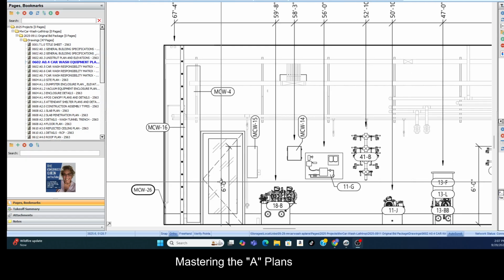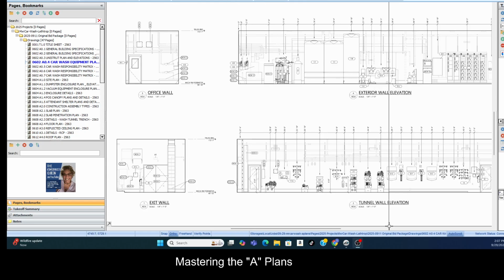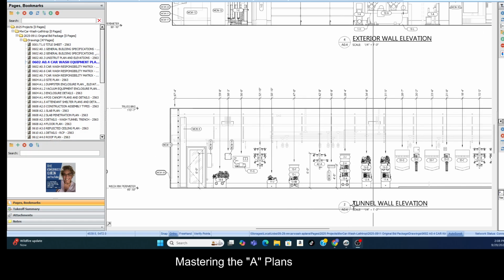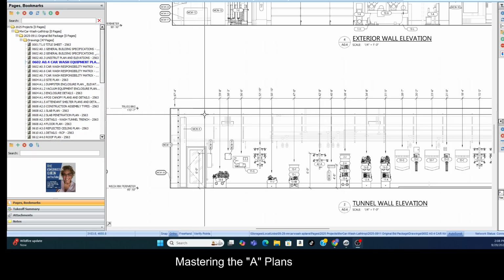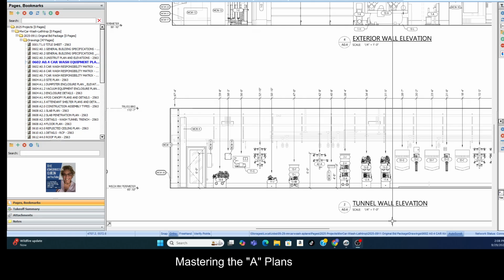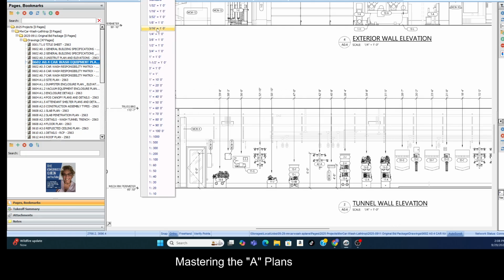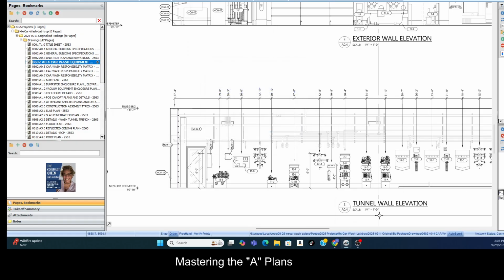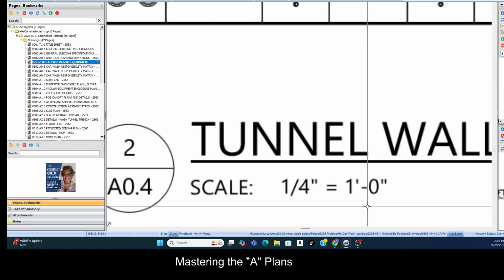The door. So now from this view, if the plans are to scale, which they are, I can tell that the building where the equipment is this height. So that'll help me a little bit. So for every 1/4 of an inch I measure, right? That's what scale means. Every sheet could be a different scale, so when you are measuring, make sure you're using the right scale.